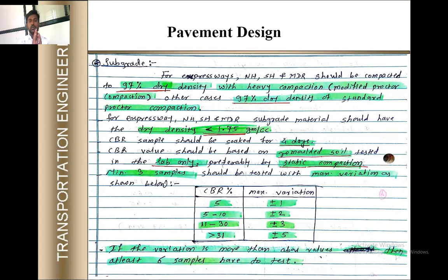The CBR sample should be soaked for 4 days. That we have seen. We have taken the CBR sample. We have to take at least 3 samples and soak them for 4 days. Then the CBR value should be based on the remolded soil tested in the lab only.